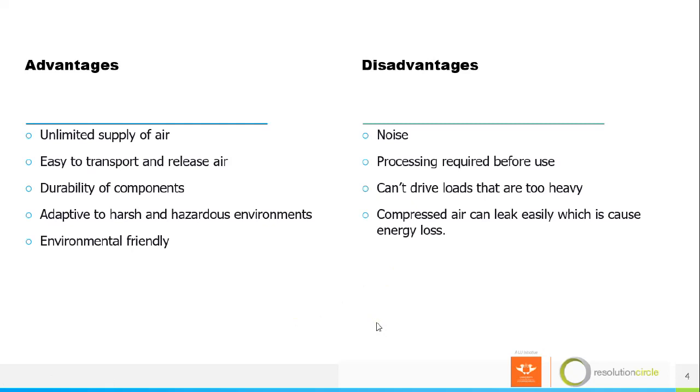You must filter that air, you must regulate it, you must lubricate it if need be. So before you can use pressurized air, it must be processed first so that it will be clean and in good standard for your system. Compressed air can also leak easily, which may cause loss of energy.